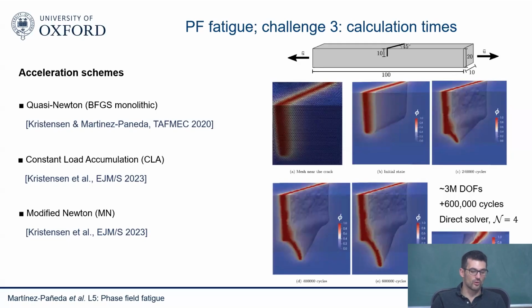And the other thing is that one of the beauties of phase field is that, if you're just going to deal with linear elastic problems where you can apply some sort of superposition and cycle jumping, you may as well do it with conventional empirical fatigue design rules. The beauty of this is that you can couple it with fatigue, with corrosion, with plasticity, with history-dependent problems that are much more complicated, hydrogen.